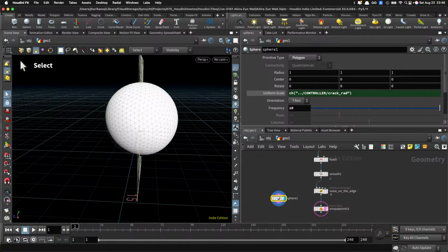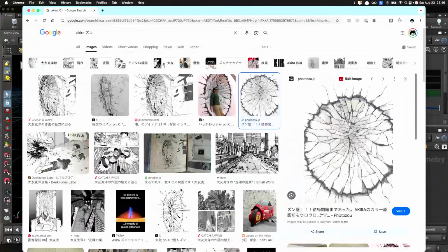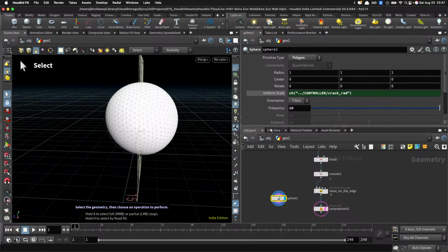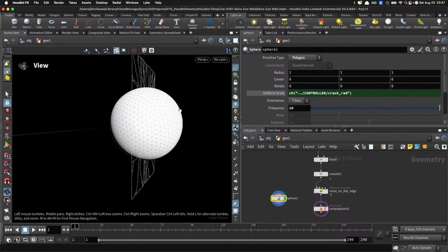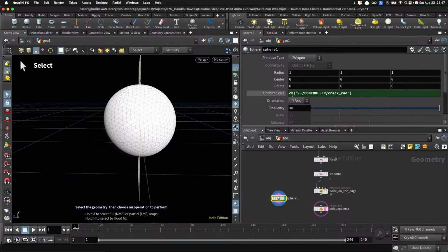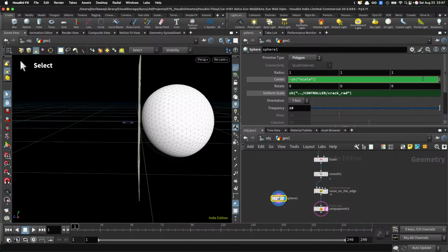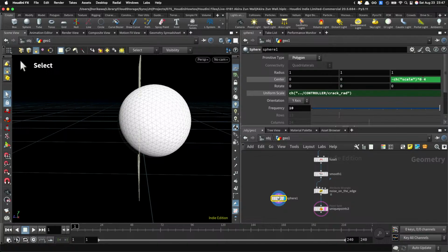And if I look at the pieces right here, you're just using the tip of the sphere in order to create the hole, in order to create the crater. So I guess I should move this sphere a little bit toward the front direction. So maybe based on the uniform scale, I'm gonna copy this, move the center to a negative z, multiply by 0.5 or 0.4.